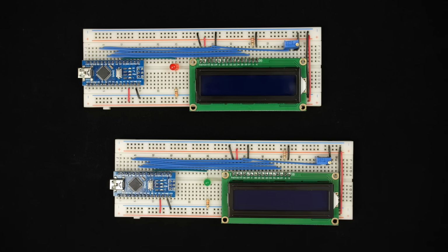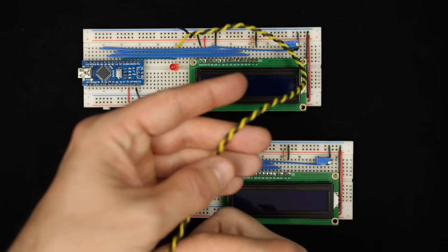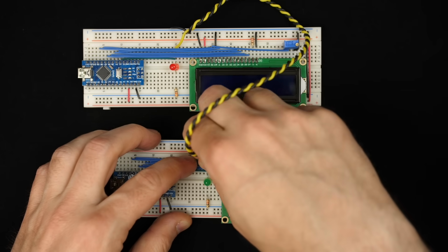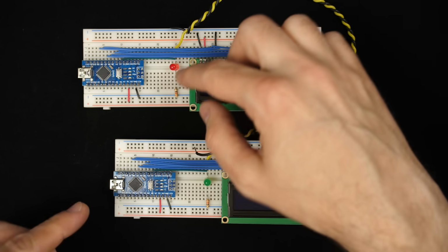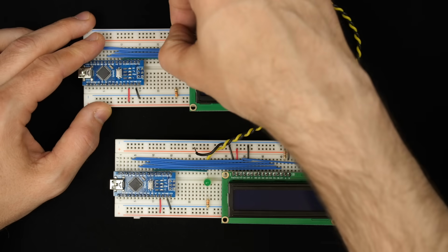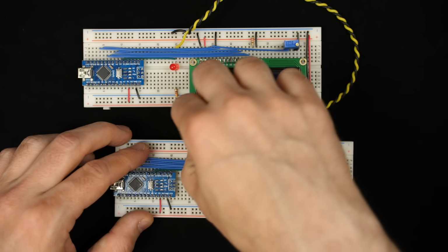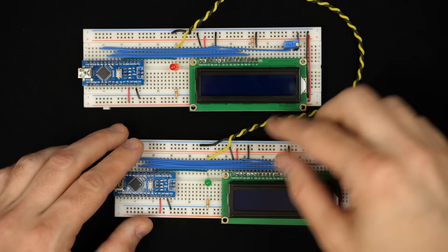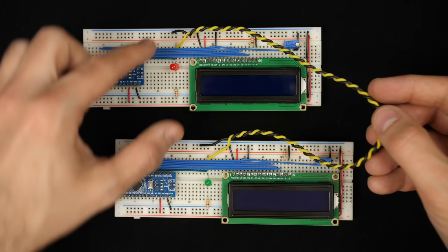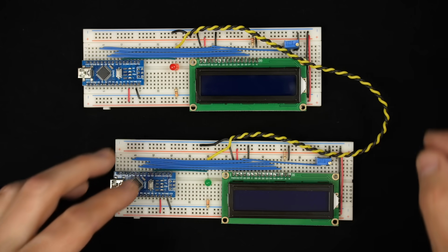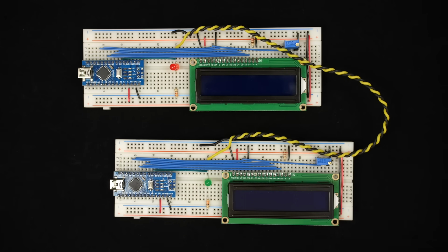And so I basically just want to hook up a wire between the data signal on the transmitter here and the data signal on our receiver. And because our signal is a voltage, and a voltage only makes sense as a difference of potential, both of these need to share the same ground potential. So in practice, what that means is that our transmitter and receiver need to be connected with 2 wires, one for the data signal and then one for the common ground. So let's power these up and see if it works.